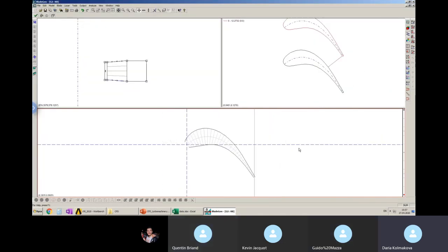So here with the rotor blade, the first rules are the same: a smooth channel and a straight shape of your profile in this area. But also, for the rotor blade, you need to consider the ratio of the areas at the hub section and at the shroud section. So the hub section has to be thicker.